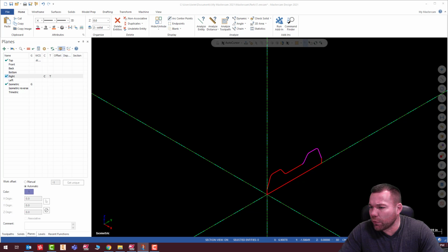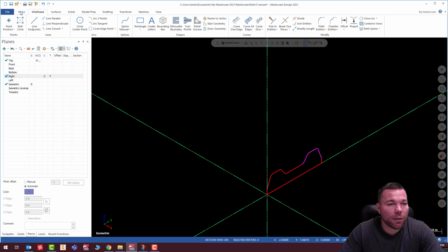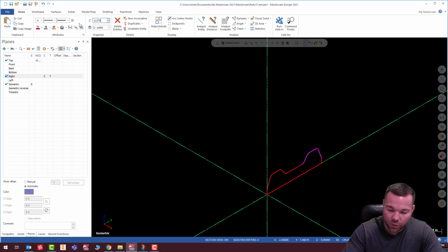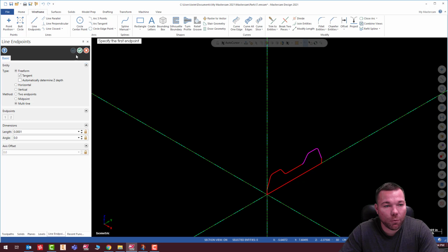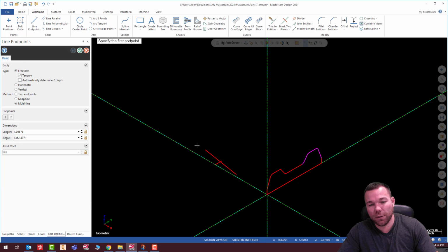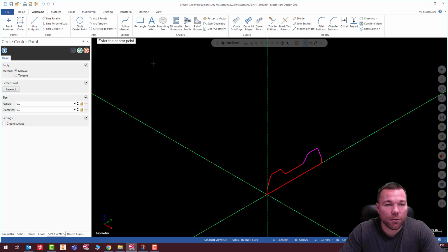All right, and also that is 2.375 in the negative. So let's go ahead and set that up. Negative 2.375. All right, and wireframe. And we're going to go from 0, 0. Helps if I press the actual line button. 0, 0. And we're going to come up to 0.3. Probably should have drawn that arc first, actually. Oops, let me get out of there. Delete. Let me draw that arc.